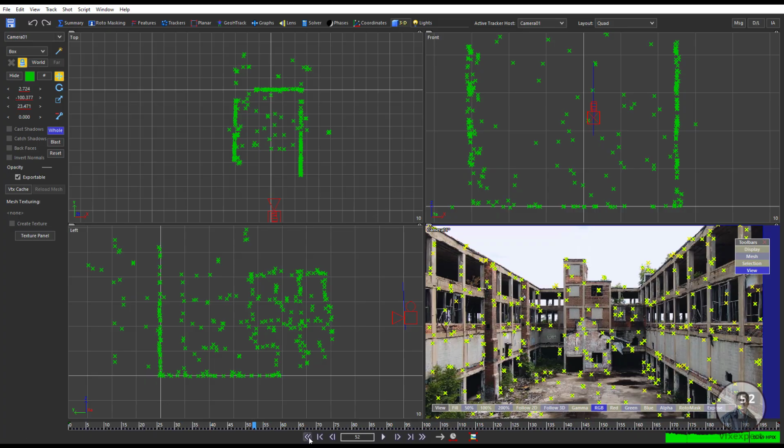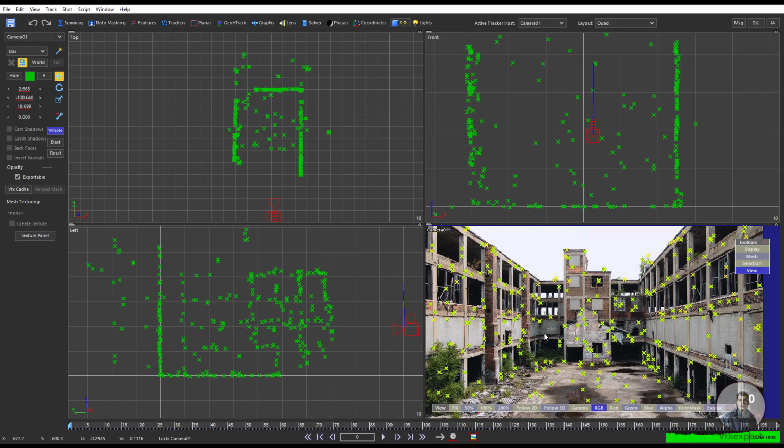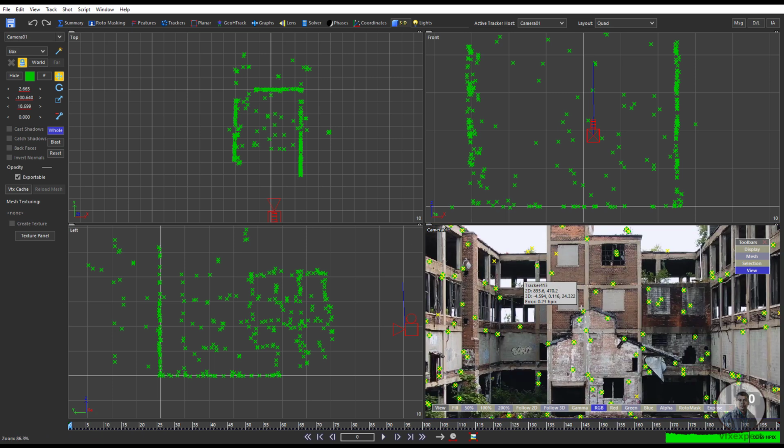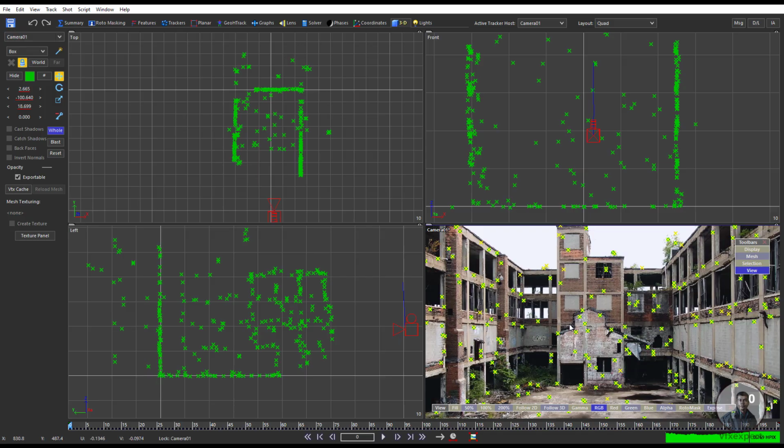Now after this I am going to create a geometry here for our scene, or test geometry. First we have to find some points. So we have to check this point position. We have to select maybe these points. Now if you try to select these points, this is not going to select because in this parameter we see this hole is checked. So we have to uncheck this one. Then you can select individual elements like these points or geometry or camera.